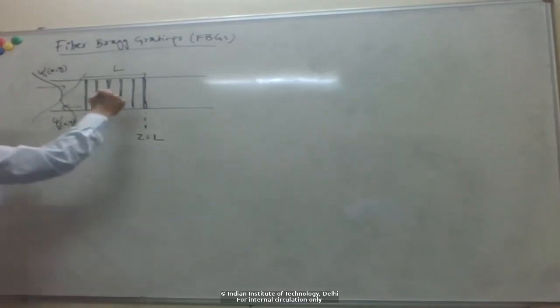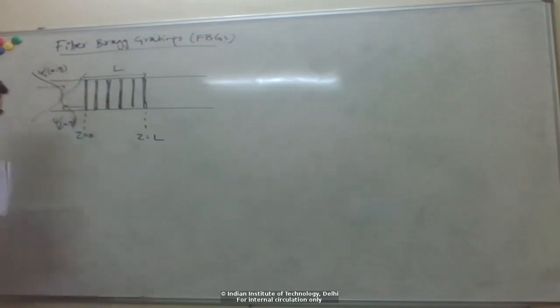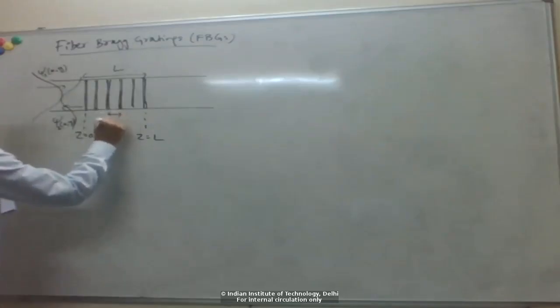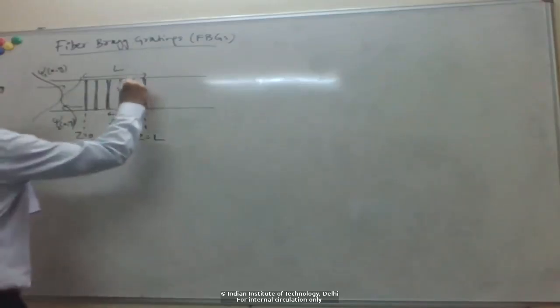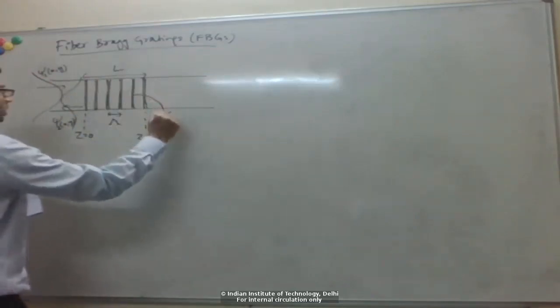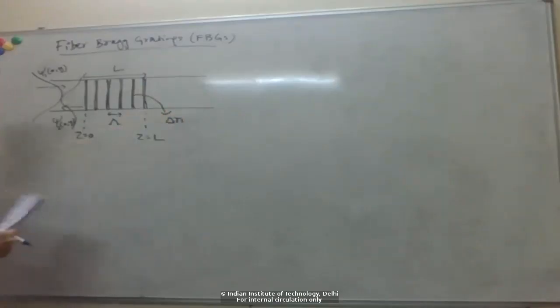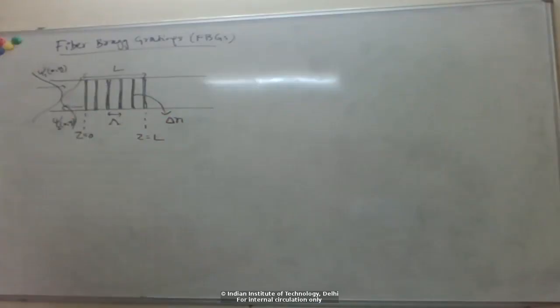And in this Bragg grating region, these two modes are coupled due to the reflection from this periodic Bragg structure, which had a period capital lambda. In these regions here, the refractive index was increased by an amount delta n due to this UV exposure, and this delta n was typically around 10 to the -4, that range.